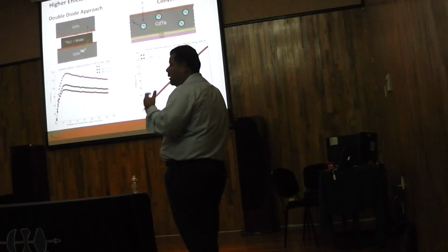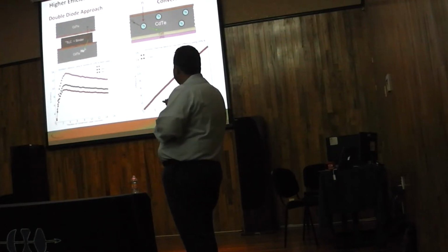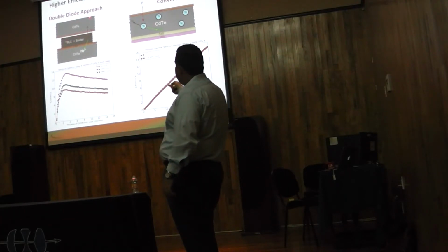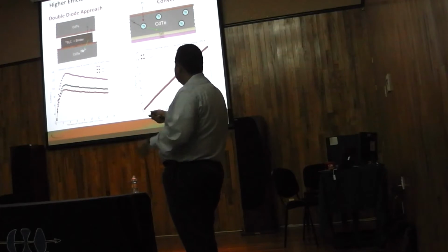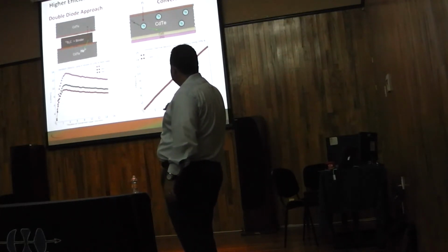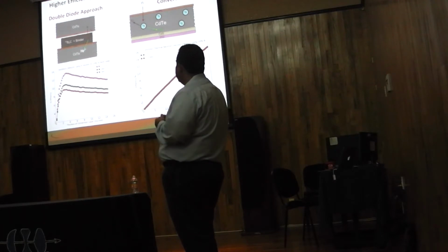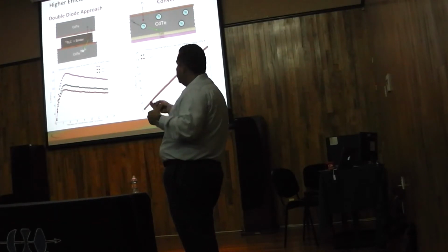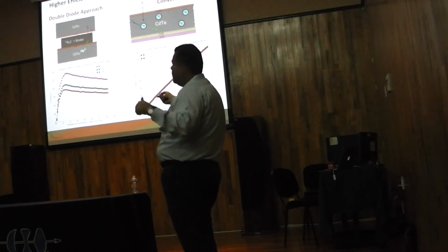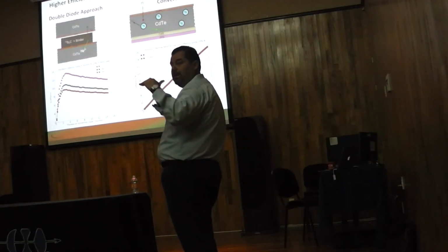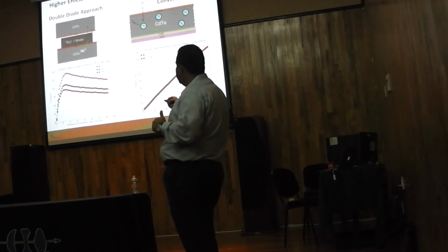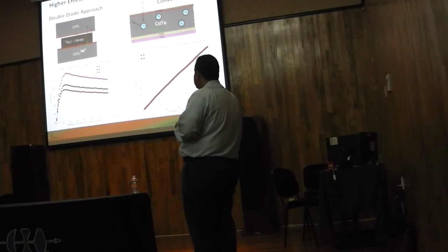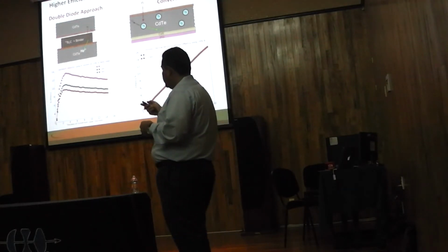The next thing is to look at the efficiency. How are we going to make this more efficient? The more efficient way is we do the sensor here. This is cadmium sulfide. Then we put the boron-10, and we put another diode on top. We call this the sandwich approach. And with the sandwich approach, we can get efficiencies in the order of 13%. If we don't use the sandwich approach, our efficiency is like 6%, or no, 7%. So ideally it should double, right, from 7 to 14. But there are some other factors in there that keep that ratio. So the efficiency reaches about 13% or so, which is close now to helium-3, which is what is used in a Geiger counter, a regular radiation detector.